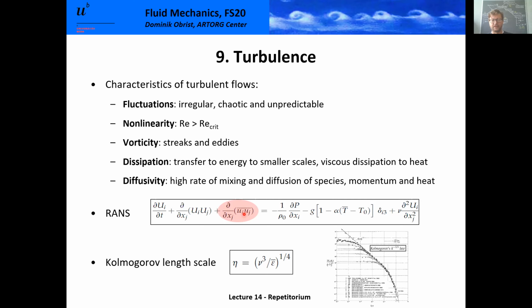So if you run a CFD code like we did last week, and you know the flow is turbulent, you will in reality only solve for the mean flow, and you will need a turbulence model to guess, if you like, what this term is. This term represents the non-described fluid structures, the unknown fluctuations. That's what many CFD codes, not all codes, are doing when they say they do turbulent flow. In reality, it's called a RANS simulation, a Reynolds averaged Navier-Stokes solution.